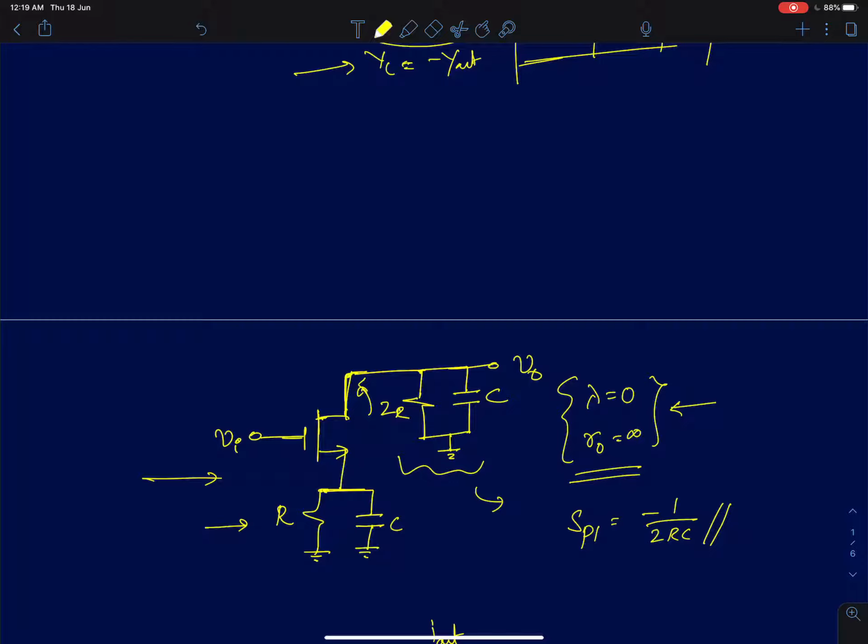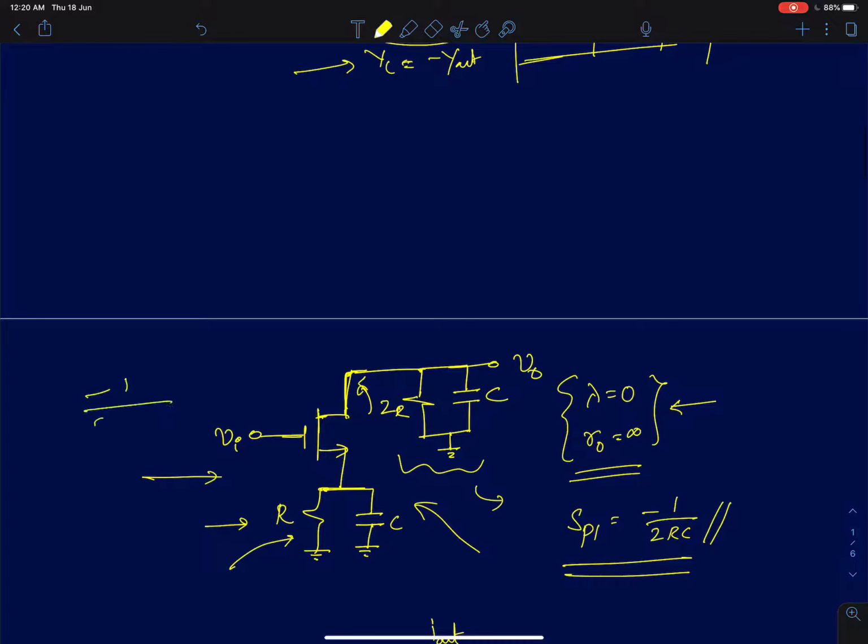Okay. So mind you, at this point, we are saying ZL becomes infinity, but you have to keep in mind your I out should not be equal to 0 at this value. If I out is 0, then we'll have a pole-zero cancellation. So if you recall from the previous lecture, we derived the condition under which I out becomes 0 is when ZS blows to infinity, and that happens at minus 1 by 2 RC. Oh, sorry, minus 1 by RC.